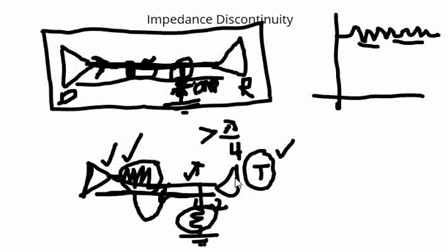Very important points, right? And when there are board to board connections, like let us assume there is a board here, and then there is a connector at the edge, and we have to connect another board. In this case, the signal will be coming to the connector, ground will be coming to the connector, and if the termination doesn't happen properly on this board, or if we are operating this board under open condition and trying to probe something here, this also might cause impedance discontinuity, which causes signal degradation.